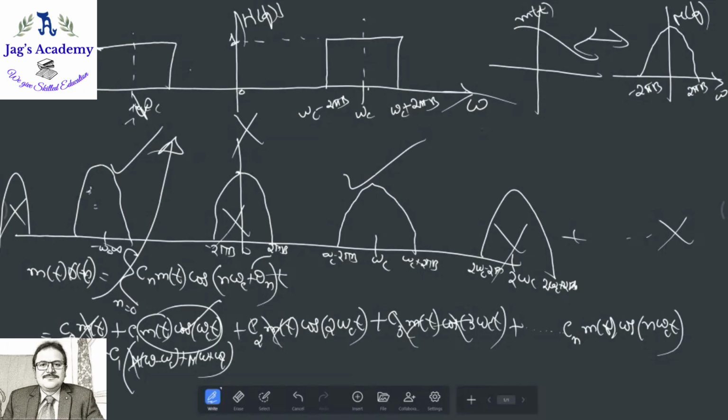I told you, this is the replica of that. It's not two band pass filters. Whenever you draw a band pass filter in the frequency domain, whatever is on this side, the same thing will come on this side. This is because of the symmetry property. Drawing only one side is not correct when you draw the Fourier transform. The other side also will be there because of the symmetric property. Have you understood this?